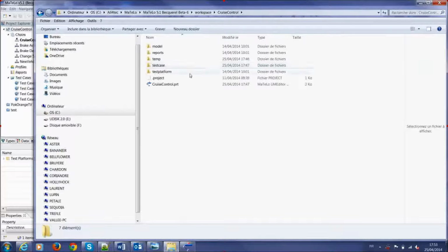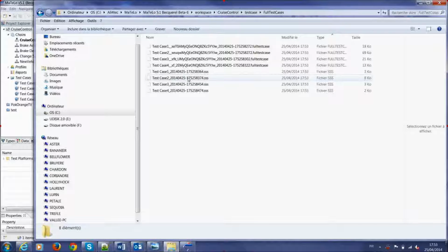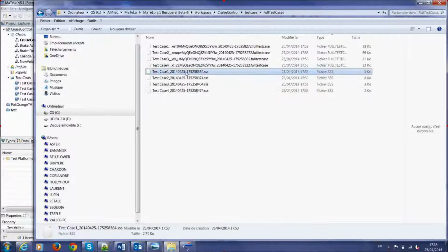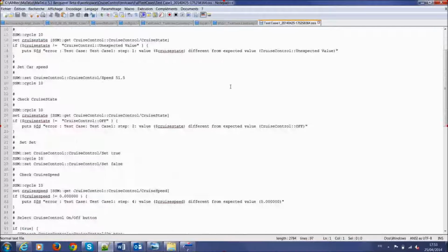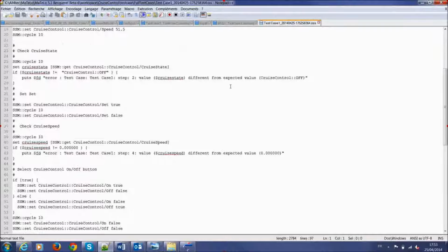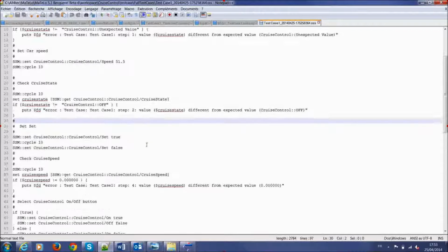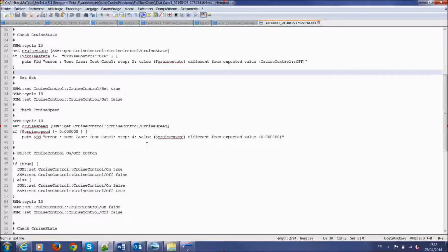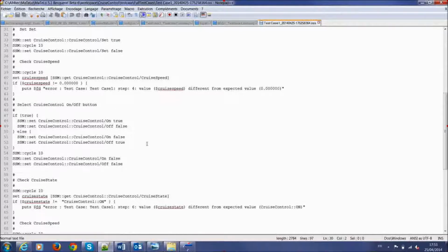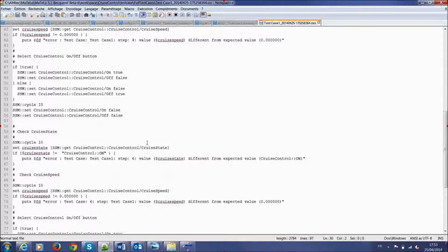You can choose the extension of the test script to be generated under the tab of the test configuration. In this example, the extension is of type SSS. The test script generated matches the different functions associated to the transitions, accordingly with the order and instantiation done in the HTML test plan previously seen. The generic parameters of the functions have been replaced by the numerical values or strings contained in the test plan.